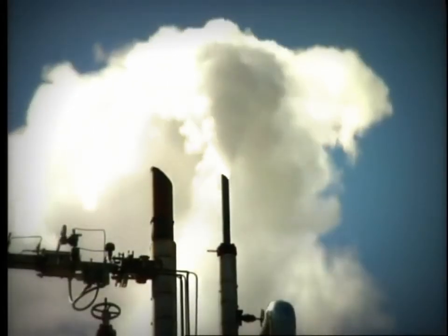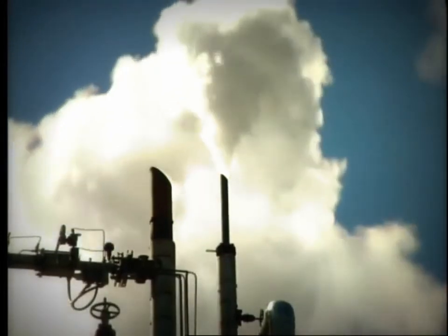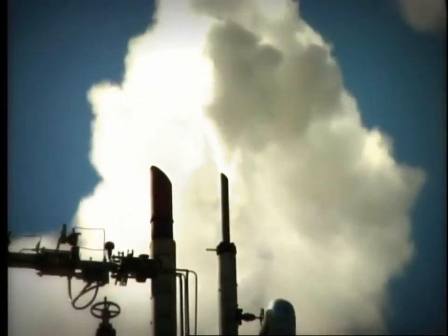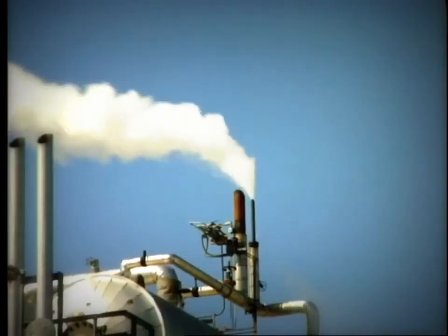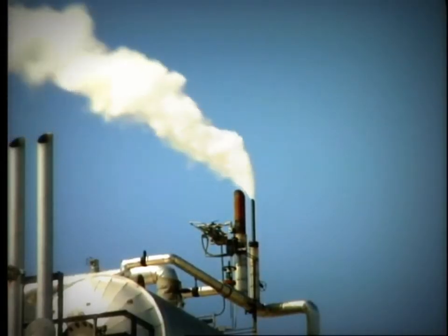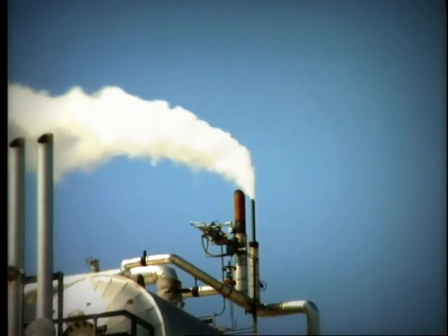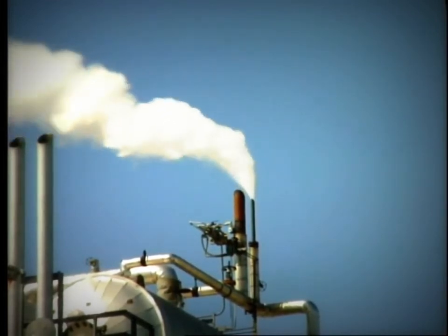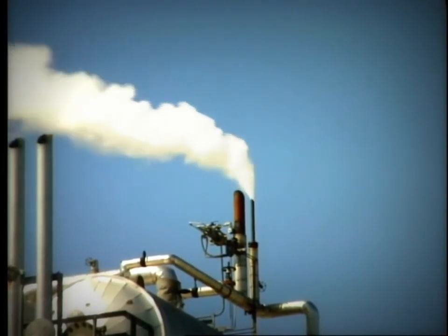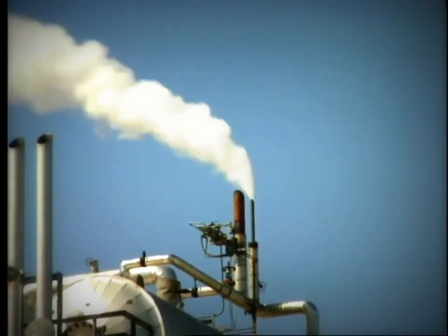The de-aerator vents may be piped to the condenser, but frequently they are released to atmosphere through a vent condenser. In this arrangement, most steam blowing to atmosphere through the vent is condensed as it passes over the condensing tubes, which transfer heat from the steam to the incoming condensate.